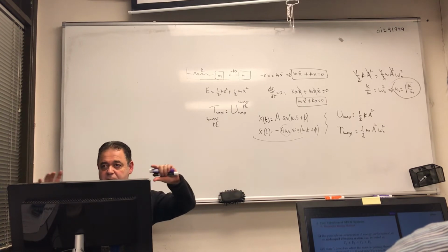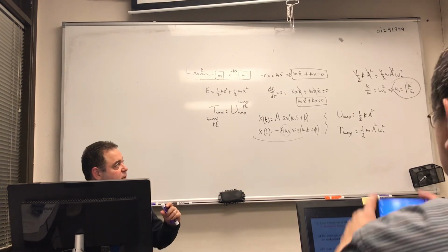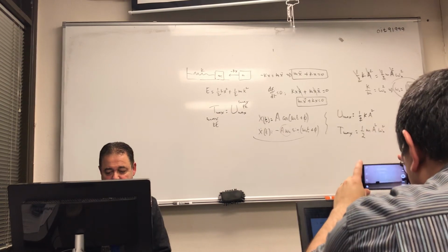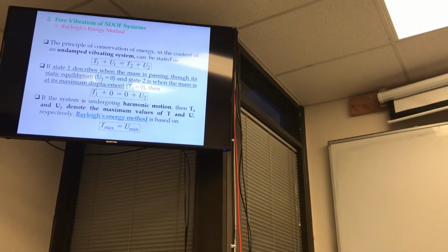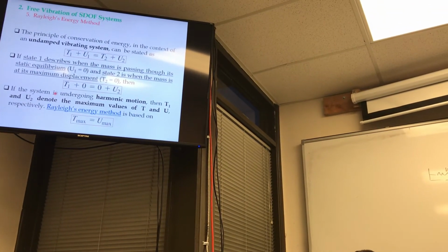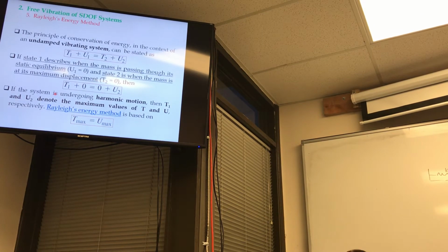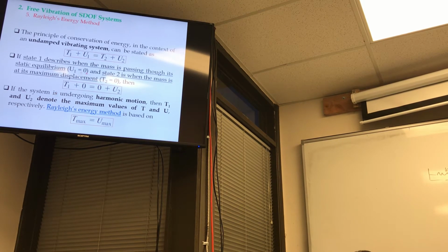When you have a big mass and then you have potential energy that is associated with that, you can actually solve the problem using this. In fact, there's one problem that is given to you here. Omega n is the natural frequency of natural vibration, and m is whatever mass is attached to the end of the spring. Okay? So in other words, without solving the equation, we are determining what the natural frequency is, without deriving the equation itself, okay? Which is really the goal of the whole thing anyways.